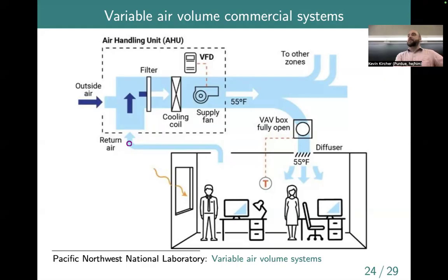And actually, CO2 concentration is a pretty good proxy for a number of other things. You can use it for occupancy. So if you have high CO2 coming back from a room, you could probably infer that the room is fairly highly occupied. You can also use it as a proxy for pathogen count. So if you're looking at the viral load, people who were working on ventilation systems for coming back to work after the COVID pandemic, right? It's expensive to try to put in an actual sensor that measures what the concentration of COVID virus particles is. But where did it come from? Okay, it comes from us exhaling. And so if you measure the amount of exhale, basically the amount of CO2, you get a reasonable estimate, I guess, of the potential viral load.